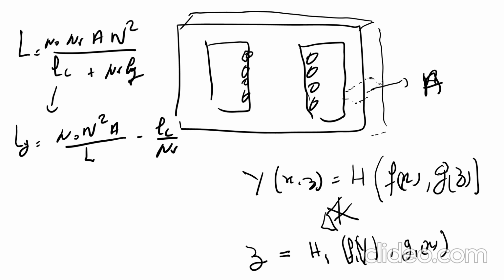In order also to explain why the air gap does not depend on the cross section, we can look at the expression of the inductance, the reluctance model of the inductance. It is a function of the cross section, the number of turns squared, the magnetic core length, the permeability, relative permeability, and the air gap. These are the main variables of the reluctance model of the inductance. Any change of any variable of this set will change the inductance.